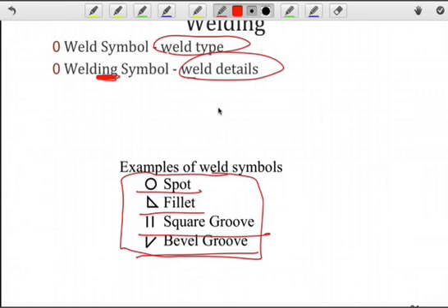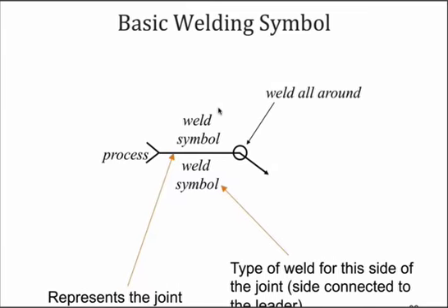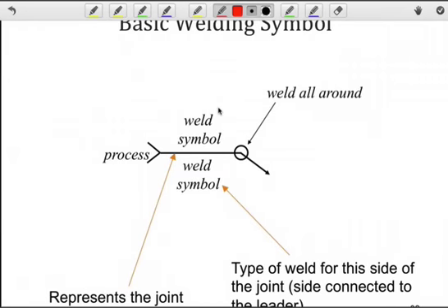You already know that you're going to go through a welding process, and so you should begin to think about your concerns related to welding and what needs to be controlled there in order to achieve the characteristics of the product. The welding symbol as opposed to the weld symbol, right? So we just looked at some weld symbols, and that weld symbol goes here and here.